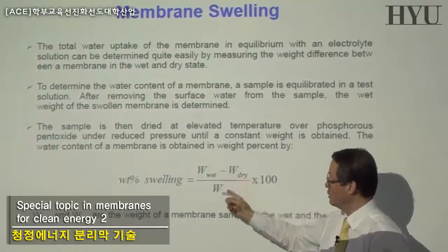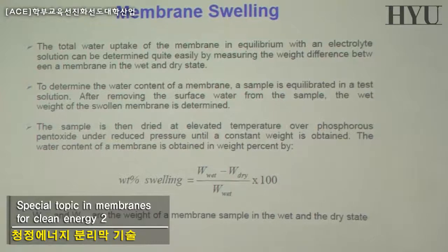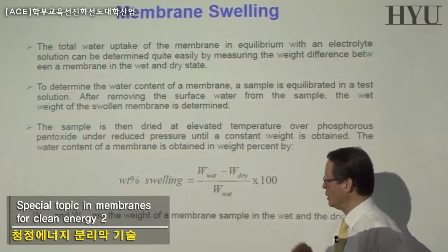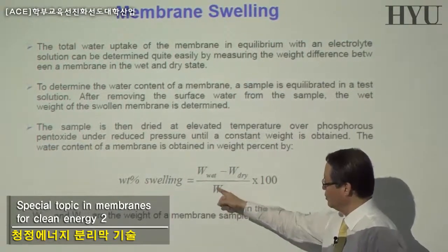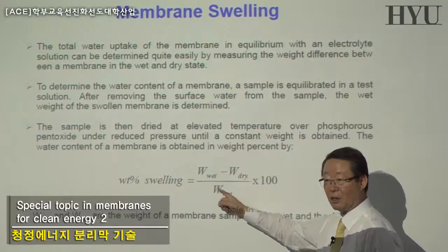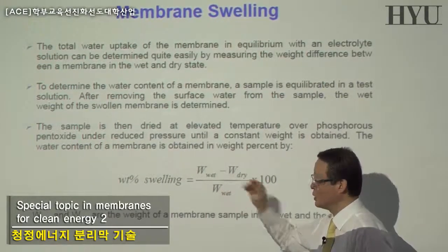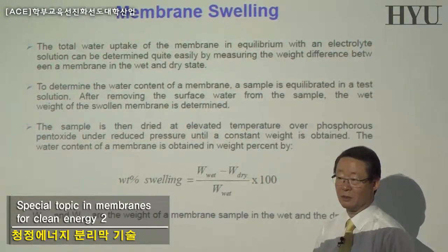And by calculating with this equation, we can determine the swelling degree based on weight. Sometimes this W wet could be replaced by W dry. Okay? So you should be very careful how they calculate the swelling degree, depending on a wet base or a dry base. Okay? Right?